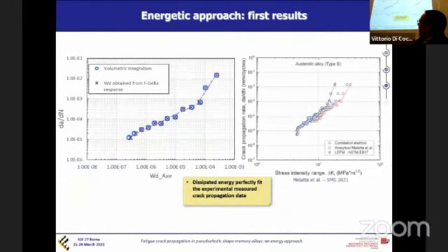And now we are trying to analyze fatigue crack propagation data as a function of these energetic parameters. And from the first result, it seems that they fit perfectly the experimental data. I mean, this parameter is able to take into account the effects of temperature and the effects of microstructure.